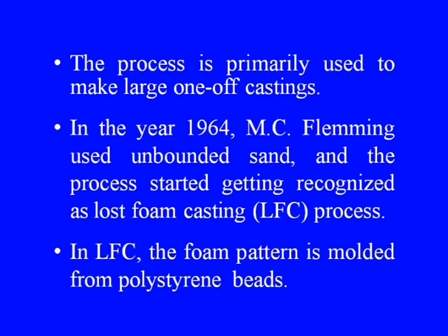In the year 1964, M.C. Fleming used unbonded sand and the process started getting recognized as the lost foam casting process, also known as the LFC process. In the LFC, the foam pattern is molded from polystyrene beads.